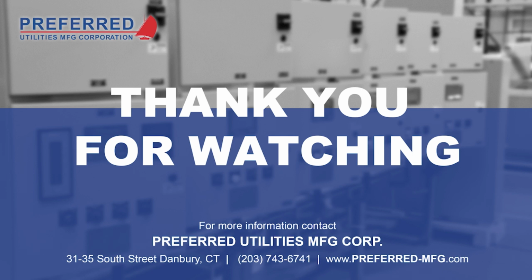Sure. Saturation most of the time will occur not so much with UV as it will with infrared type scanners, but what it amounts to, quite honestly, is you've just got so much signal that it's overloading the front end of the flame safeguard. And in particular with infrared, if it's so massive, it becomes a signal that it can't see the fluctuation. And it needs to see that amplitude fluctuation to know that it's truly combustion or flame versus refractory.